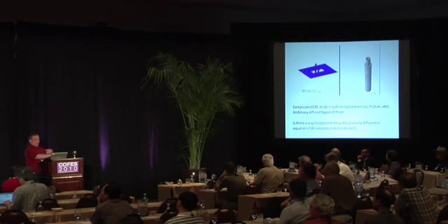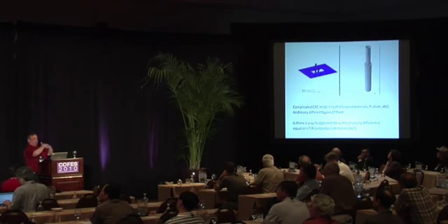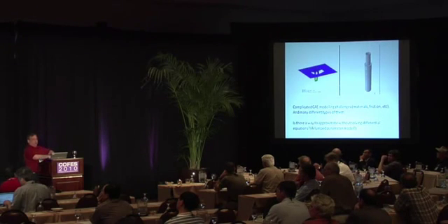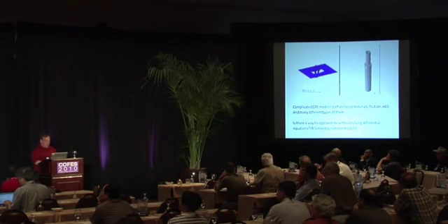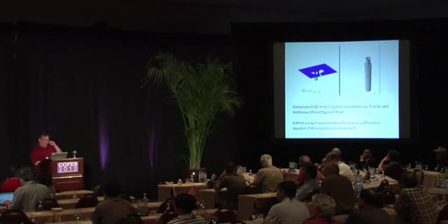And if the clip is attached to a trim part, and the clip is not completely inserted by the time the trim part comes down into contact with this boundary condition, then I actually have to start to deform the trim part in order to push it in far enough to complete the insertion, and that's what gives rise to these excessive forces. So this is the first step at being able to analyze that.